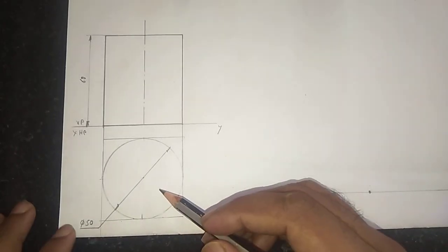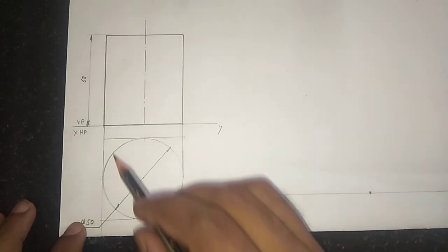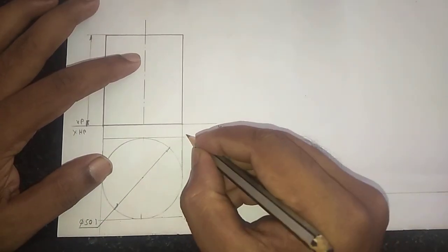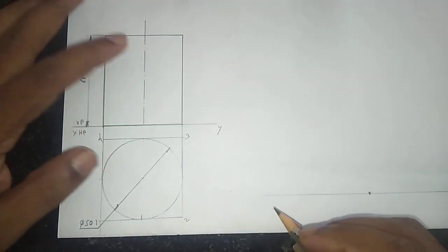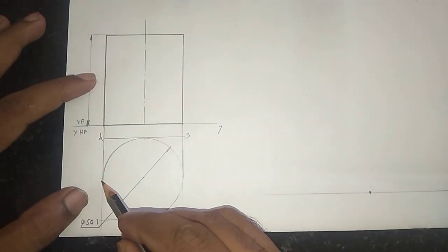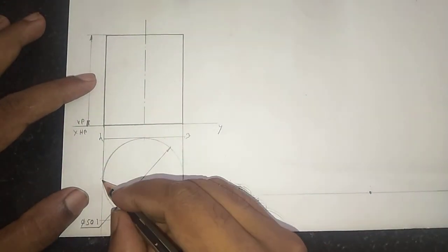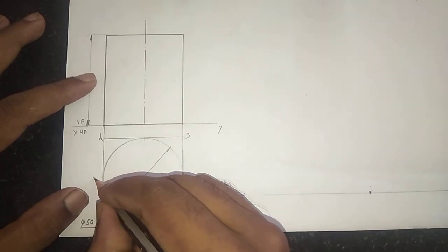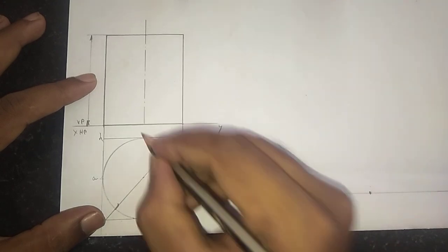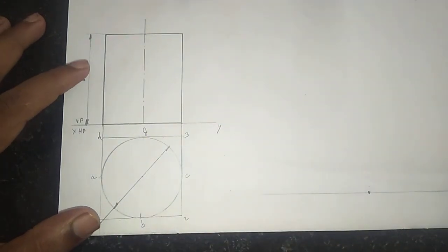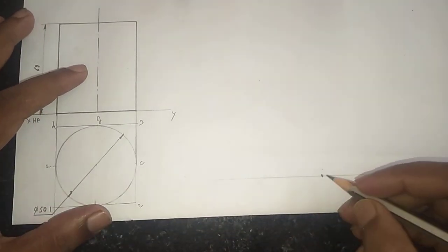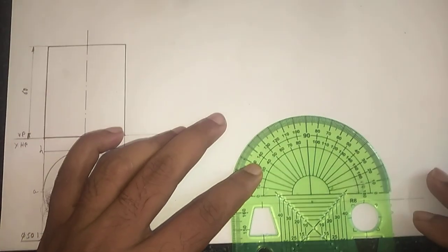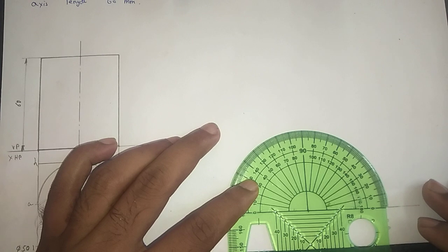So like this we accommodate the cylinder into a square box and give numbers here 1, 2, 3 and 4, and also in this place where the circle contacts the box, we give the names A, B, C, D. And now in the straight line mark one point and place the protractor on the point and take an angle of 30 degree on both the sides.